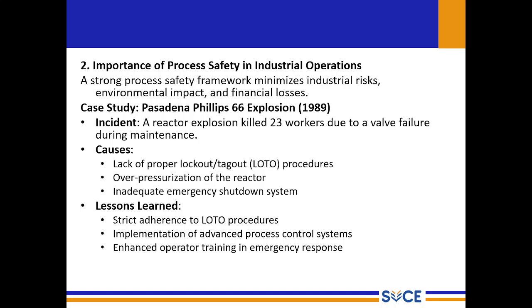So what is the implementation of advanced process control systems we can go for? Modern process control systems monitor reactor conditions in real time and automatically shut down operations if pressure levels become unsafe. Digital safety interlocks should be used to prevent over pressurization, right?